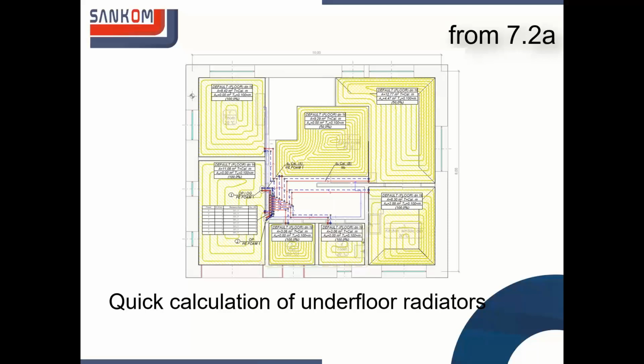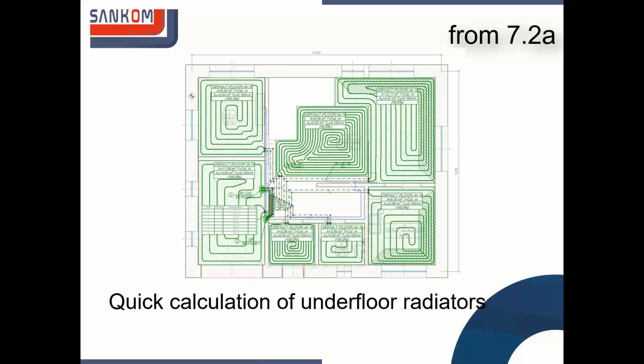You don't need any complete piping system. You just need radiators, underfloor radiators in this case, and it would be good if they are also in some rooms where the program knows the heat load. So then you can select a group of radiators. For example, Control A, you can select everything, if you are in the system mode, so everything means the elements of the heating systems only.